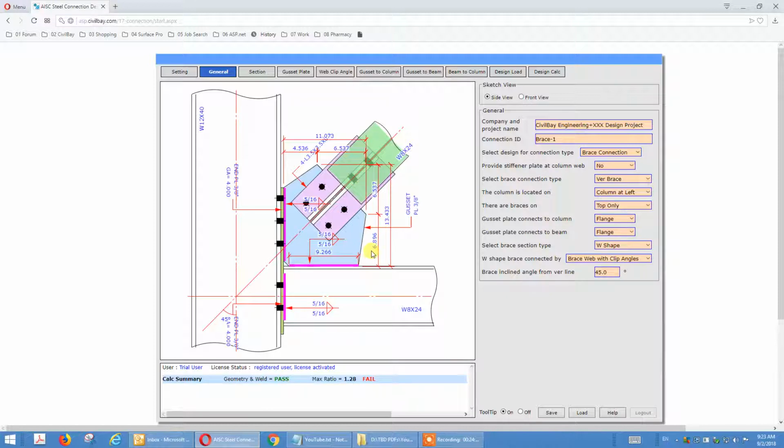Okay, that's not common, the same ways of connecting wide flange to gusset. We do this when this wide flange brace is X type cross bracing. Okay. When you go to X type cross bracing, your in-plane brace length is cut to half, and your out-of-plane brace length is full length.